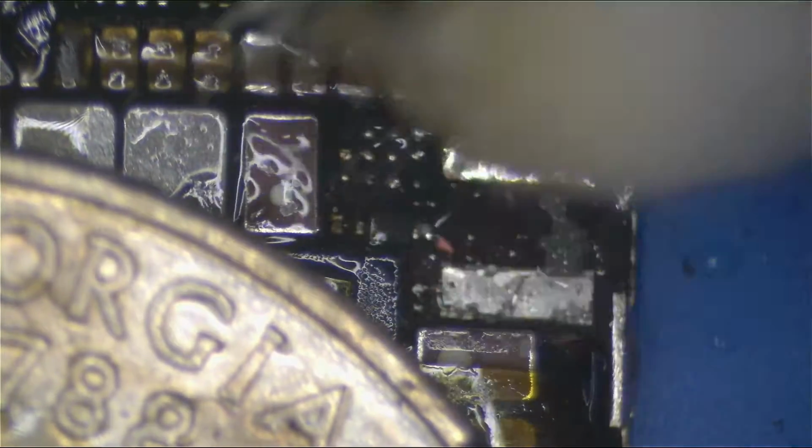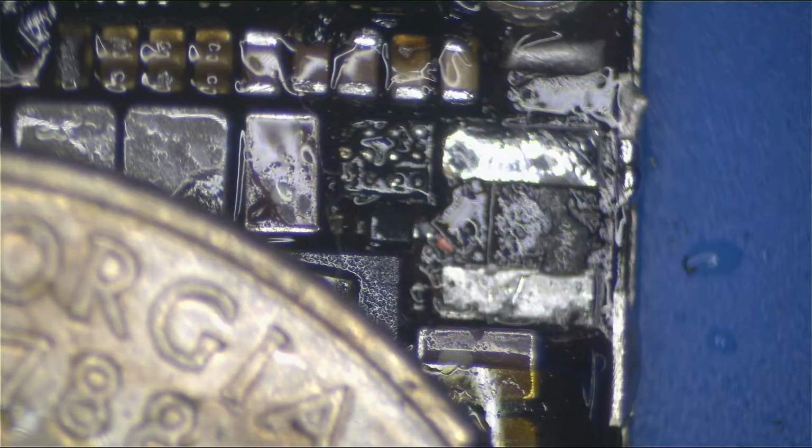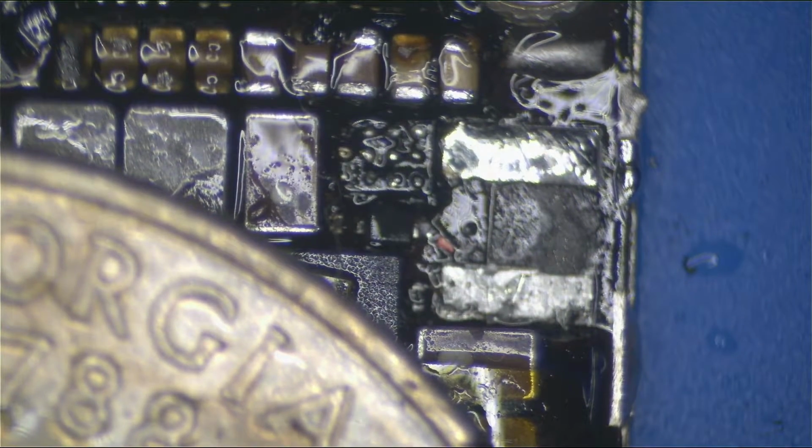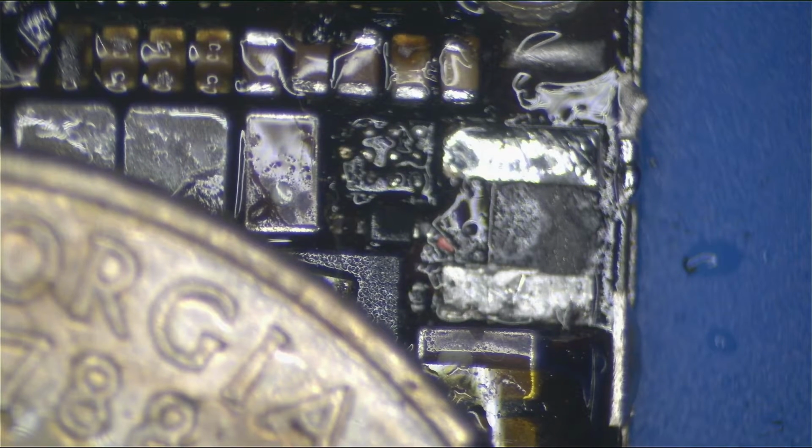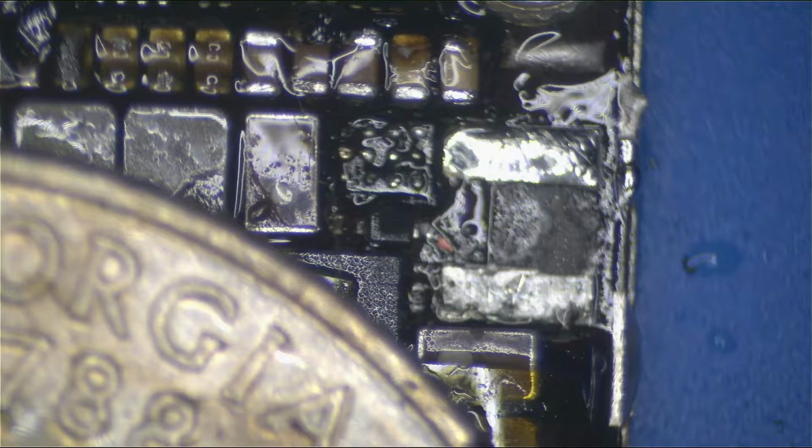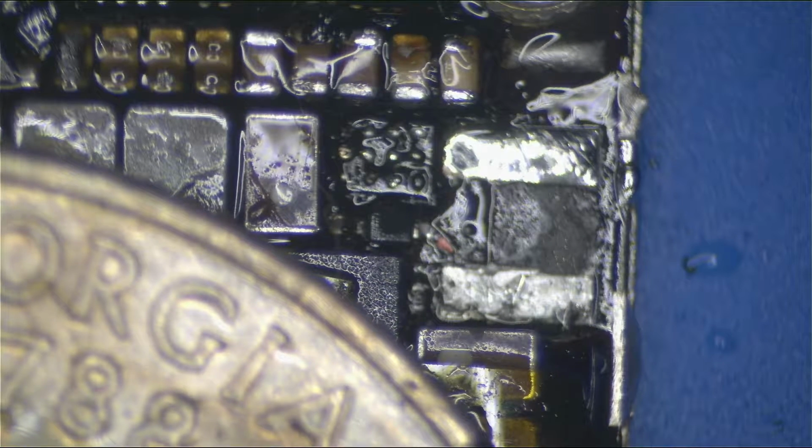The problem with wicking them is, I'm not a competent wicker. I don't know if that's a word, but I don't wanna risk it when I can. And now you can also see there's still underfill left from under the chip, so that has to go too. So what I'm going to do is just use my hot tweezer tips and just start picking that away gently.